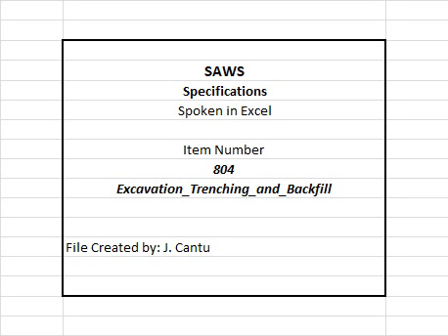requirements specified. A. Initial backfill is defined as backfill having a thickness in its compacted state from the surface of the bedding to a point 1 foot above the top of the pipe. B. Initial bedding material shall be consolidated to assure it is incorporated from the bottom of the trench up to the pipe center line. 1. A handheld vibrator, commonly used for concrete work, can be used for this purpose. The vibrator shall be inserted every 3 feet on each side of the pipe.